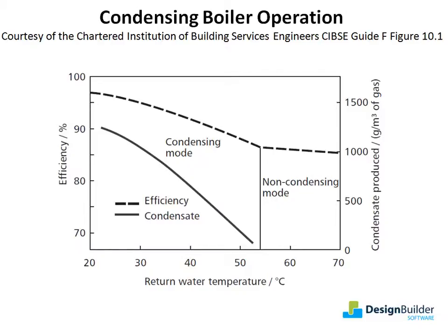The maximum output from a floor heating system is much lower than many other types of heating system and may not be sufficient to meet the higher heating loads in older, poorly insulated and leaky buildings. Floor heating requires an insulation layer below the embedded tubes to prevent heat leakage downwards.